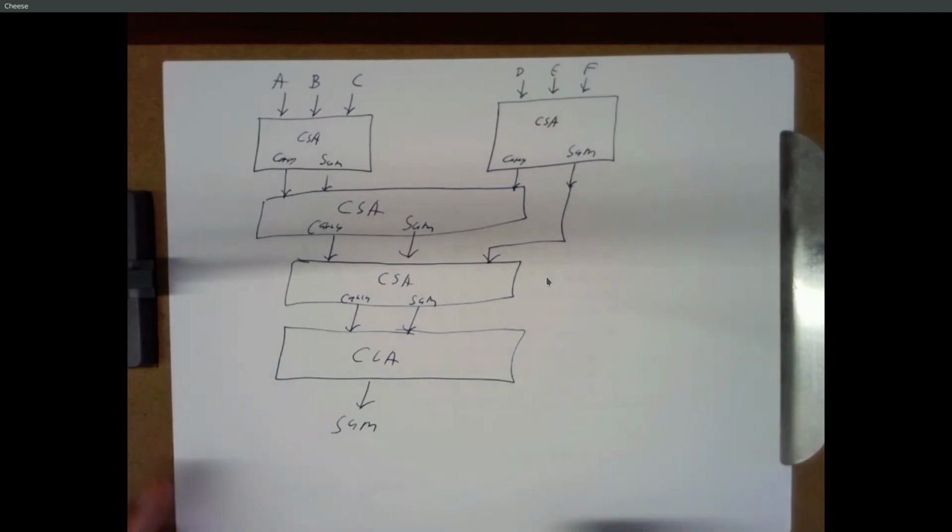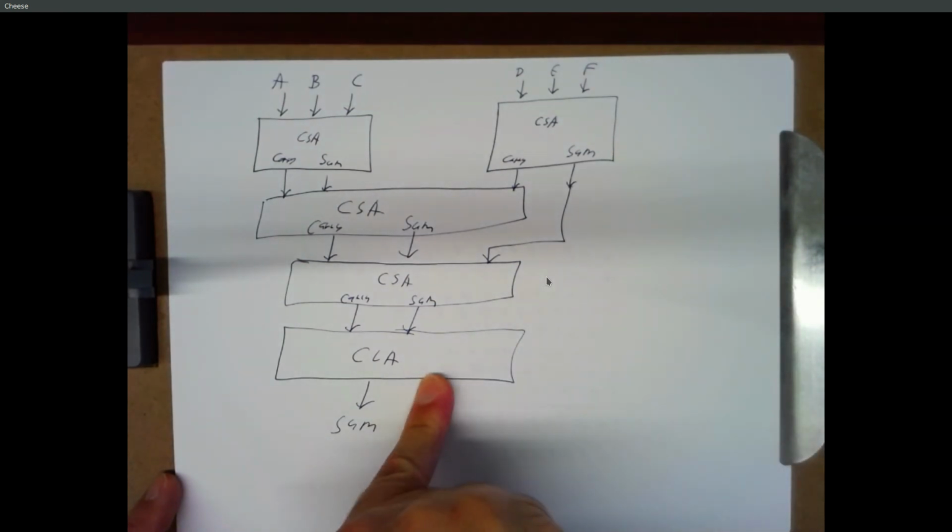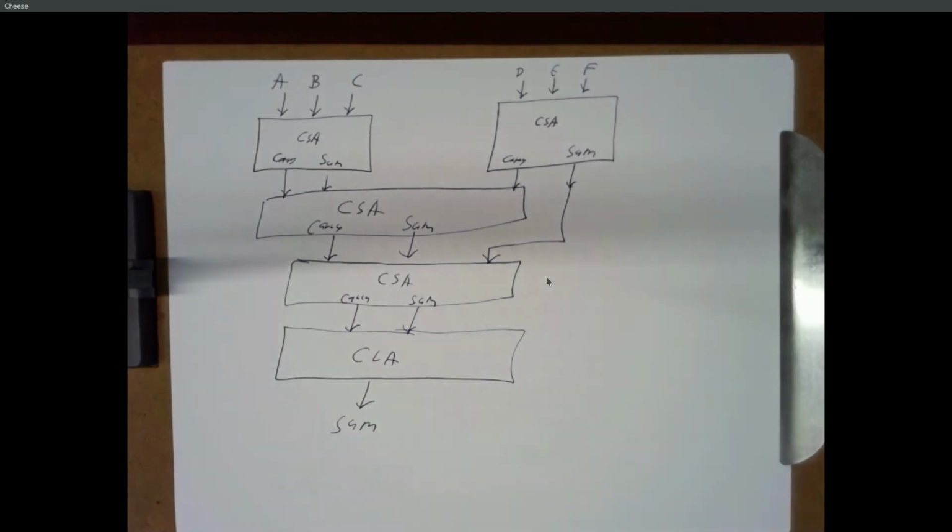And in terms of propagation delays, 1, 2, 3, 4 additions instead of 6. So that's like 50% faster. 33% faster. And this is logarithmic. If you were trying to add 1,000 numbers, you would end up with on the order of 10 additions instead of 1,000. Right? So the more things you're trying to add, the bigger the payoff for this. Now, if you're multiplying 32-bit integers, you end up with 32 partial products that you have to add. So 32 additions, long propagation delay, versus a Wallace tree, 5 or 6 additions, significantly faster.